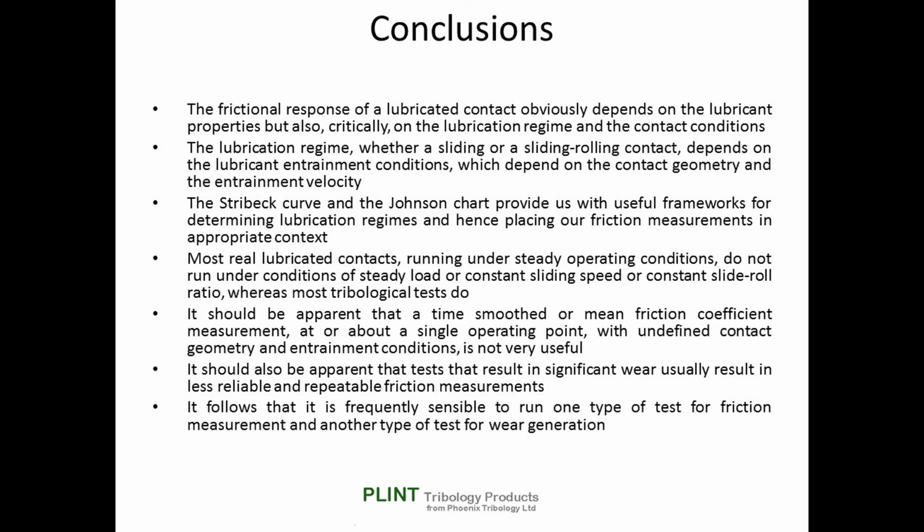It follows that it is frequently sensible to run one type of test for friction measurement and another type of test for wear generation. The many parameters that affect frictional response of a lubricated contact make the very notion of a lubricated friction coefficient more or less meaningless.